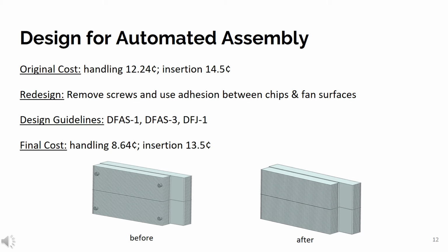Upon redesign, the screws were replaced with thermal adhesive compound placed on either side of the 4 thermal chips, holding the subsystem together. Leveraging design guidelines DFAS1, DFAS3, and DFJ1, the final handling and insertion costs were reduced to 8.64 cents and 13.5 cents per part, respectively.